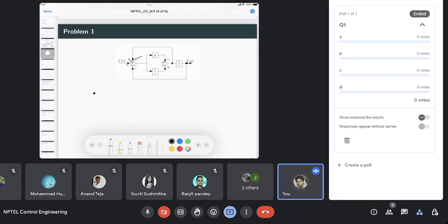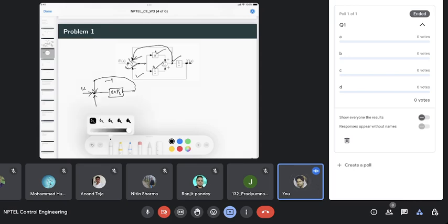So at this point you have one input, which is u. Another is you're feeding back some signal there, we'll write that, and another signal is this one also, we'll just write. Inside that we have this and this, which you can just write as an addition, because this is just simple addition, S plus 1 by S. Then you are picking that signal here and giving it as negative feedback, so this gain is -1 there.